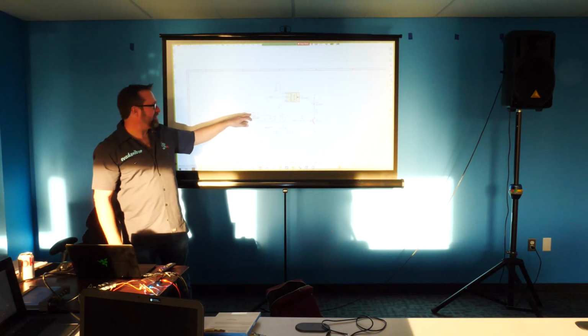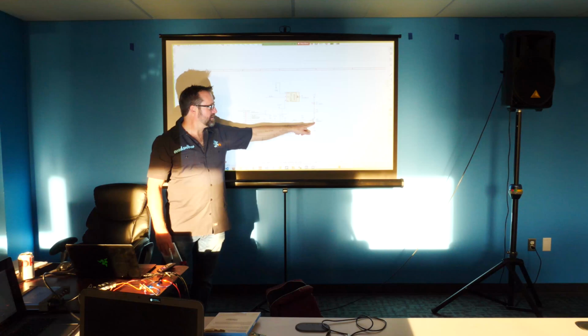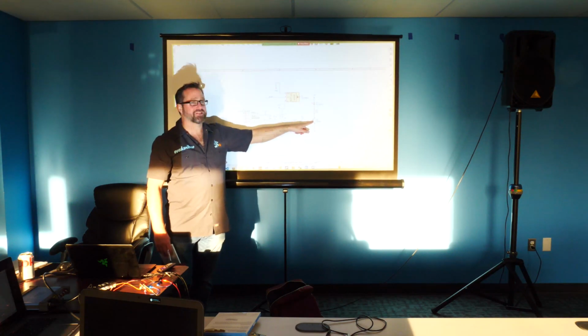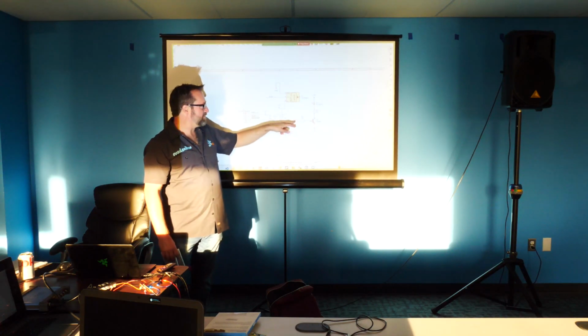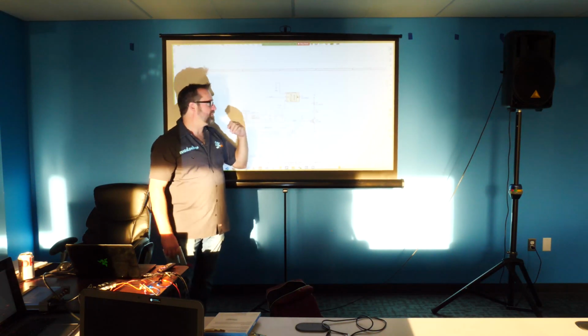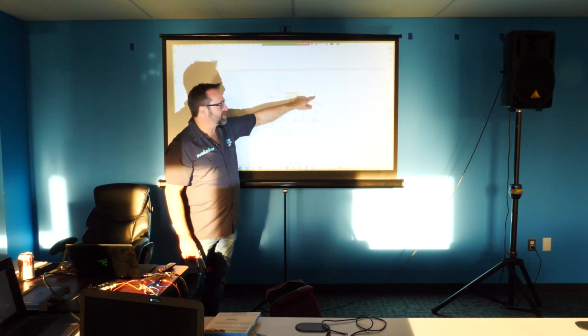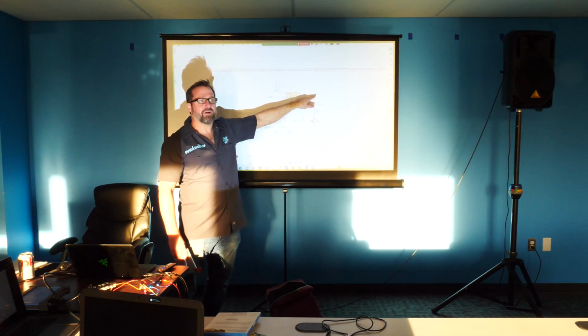So instead of just driving the pin directly, we actually drive it through a transistor driver. So basically this is just an amplifier. So a small amount of current, this will generate 100 times the amount of current, basically. Basically this is a driver. We also run it at 5 volts to give it a little bit more power.